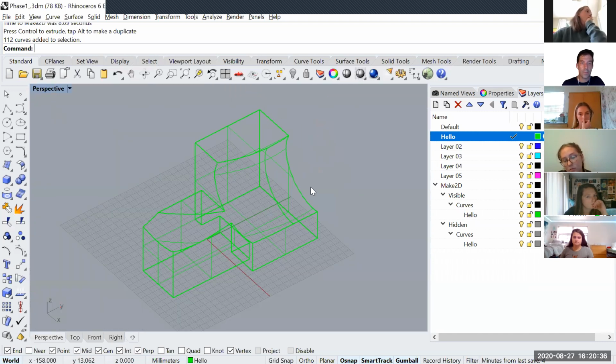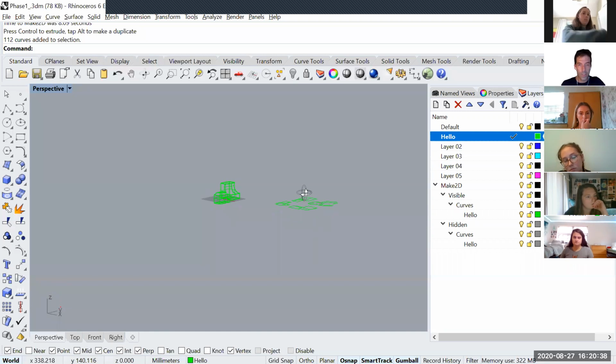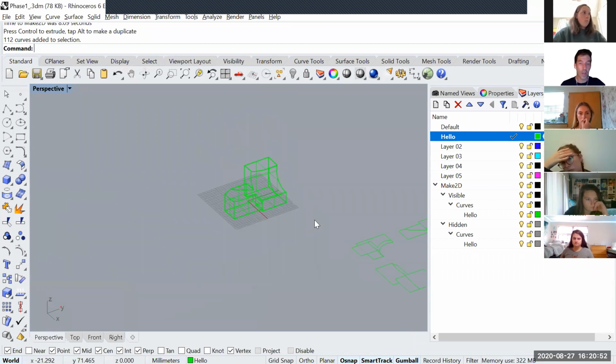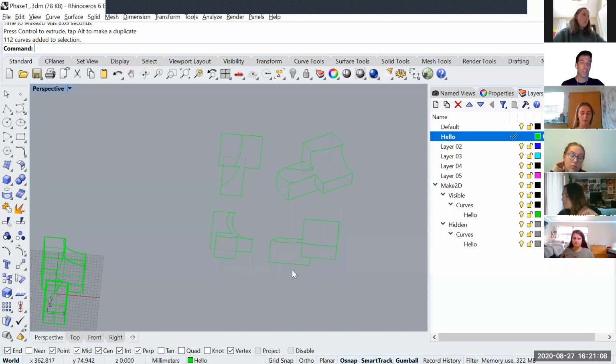I go to perspective. Notice that it's actually a planar set of lines and curves. So what the Make2D command does is take the view that we have and create a drawing of that view, and a drawing of the top, right, and back views. Some of the elevations, the top view, and the axonometric of an object. These drawings, we want them in InDesign at the end.